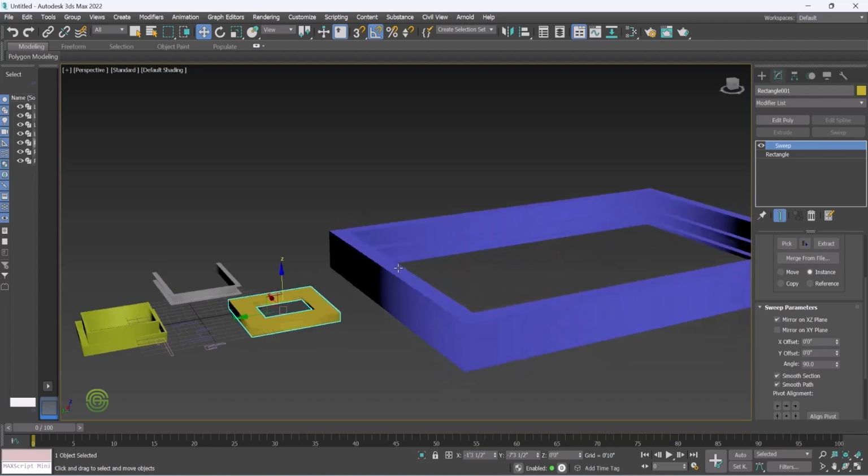So in this class, we learned how to create shapes with rendering. In the previous class, we learned how to convert 2D shapes to 3D by using extrude. In this class, we learned about 2D shapes with the rendering option. Just by clicking on rendering, we can make it a 3D object, as a rectangular or radial cube.